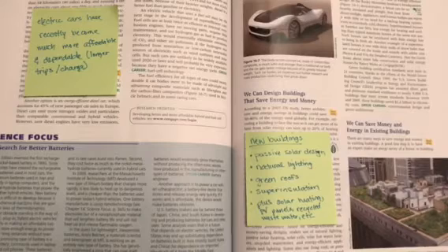So with new buildings and new construction, you can take advantage of passive solar design. So that's things like having the building primarily facing south so that you get more sunlight, but then also having overhangs, etc. There's a description of one building in the textbook, covered it up with my Post-it. But in the summer months, the sun is blocked, but in the winter months when the sun is lower, you actually get more of that heat.